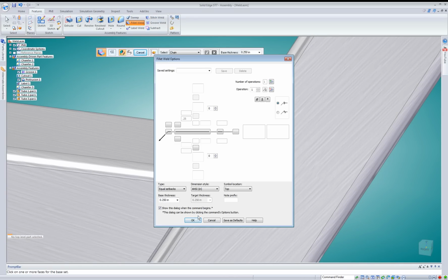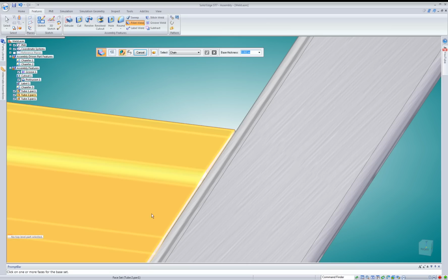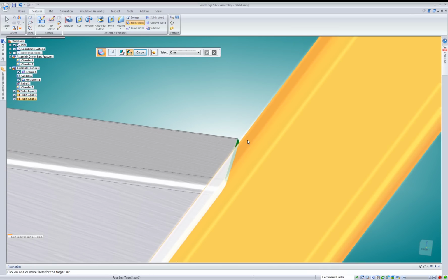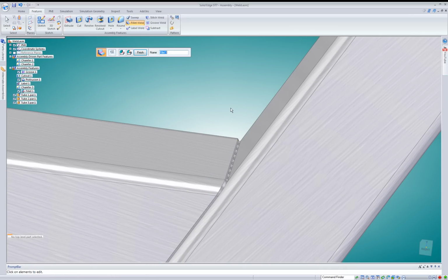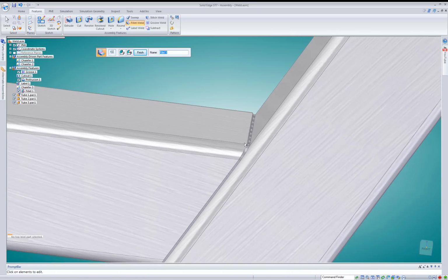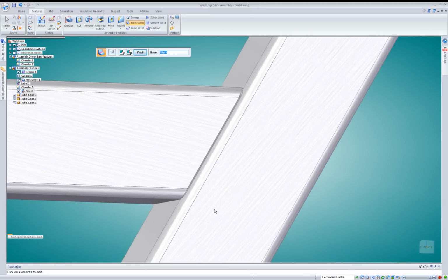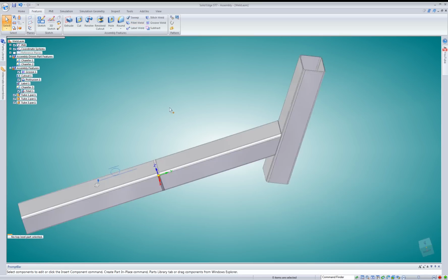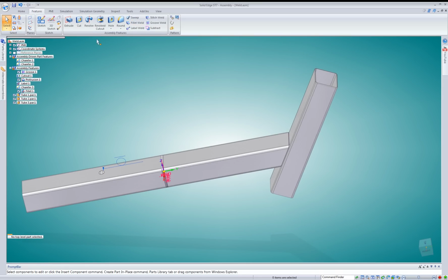And let's just throw a couple weld beads on here. We'll just do a fillet weld. And let's see, base thickness point. Same as the chamfer here. So I'll just go ahead and say, let's put a weld bead on this face and that face right there. There we go. I could actually make that weld bead a little thicker, but I could go ahead and just create that weld bead all around if I wanted to, or just on the faces that I select. So here we go. So that again is the 3 different types of features that we have in our assembly.